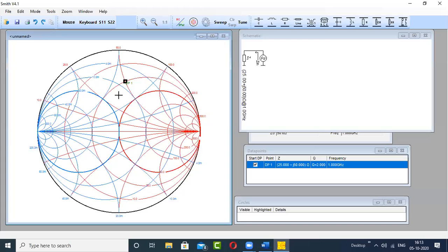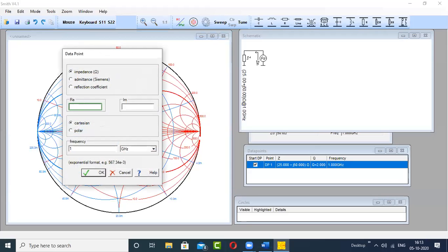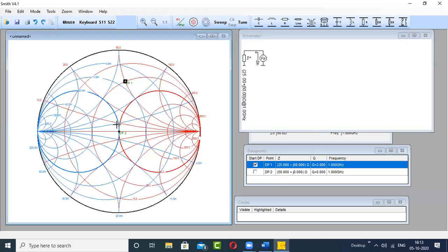Now, the alternate way is what? We have been taking the help of the blue circle to reach the center of the Smith chart. In the other two cases, we can take the help of red circles to reach the center of the Smith chart. For that, since your load is present here, you have to jump from this circle to this dark red circle.